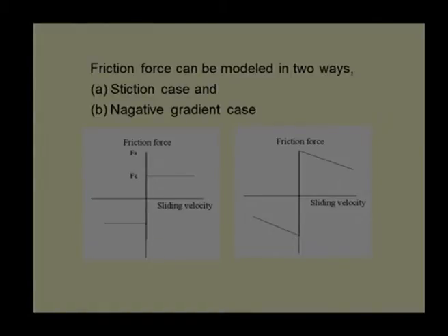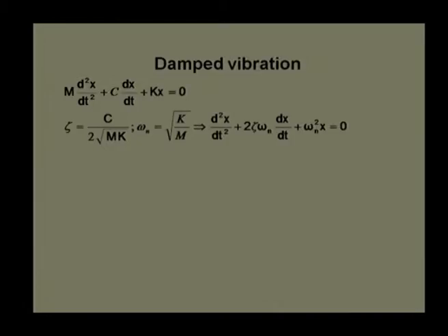To consider this in the right manner, we will start with a common equation which we generally use for damped vibration. We know this is a second order equation, but here we are using only x, taking only one direction, so it can be converted into a differential equation. M is the mass, C is the viscous damping coefficient, and K is the system stiffness attaching the block.